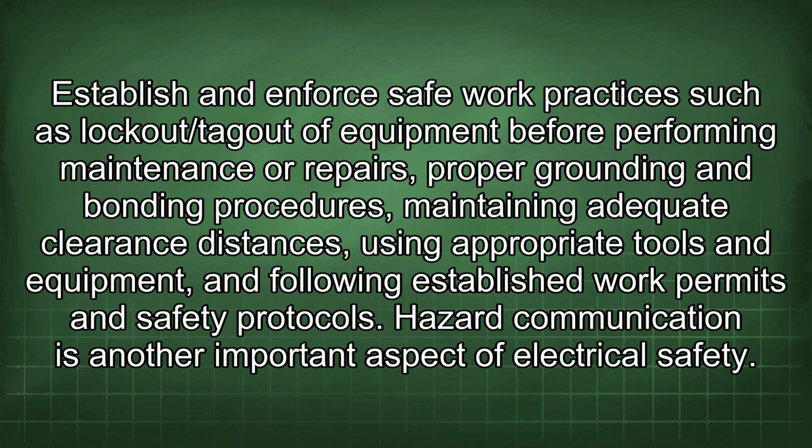Establish and enforce safe work practices such as lockout/tagout of equipment before performing maintenance or repairs, proper grounding and bonding procedures, maintaining adequate clearance distances, using appropriate tools and equipment, and following established work permits and safety protocols.